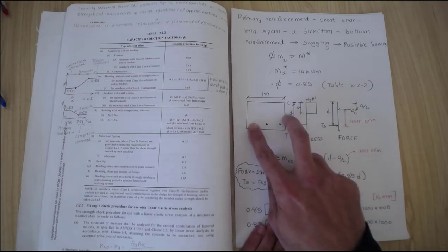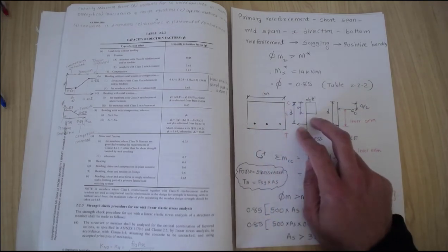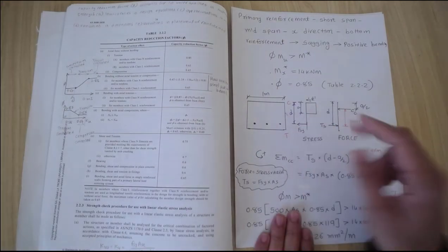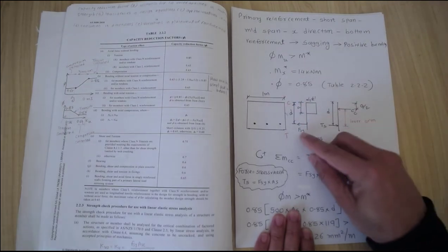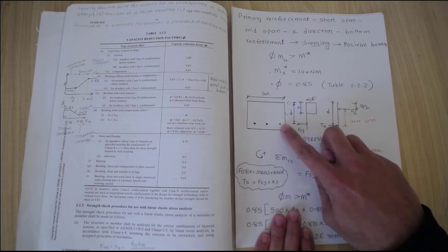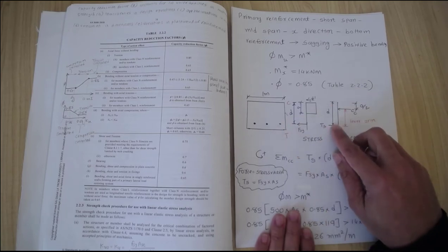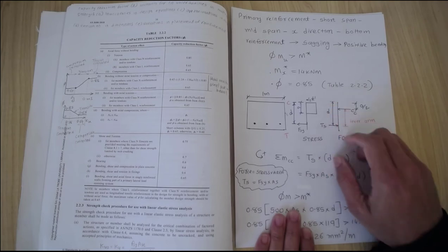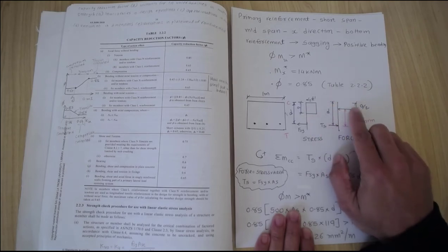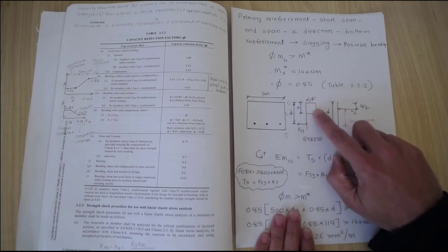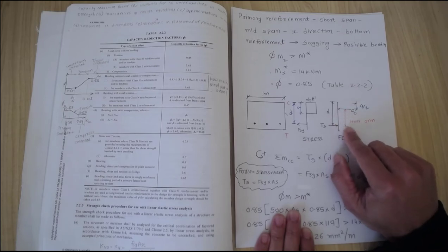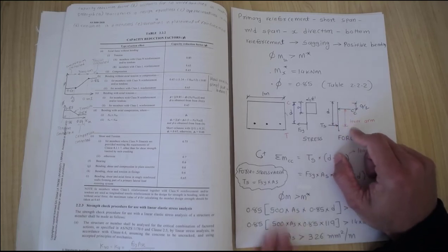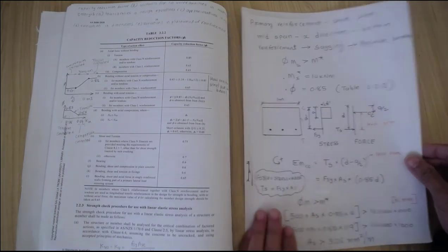Now if you remember this kind of stress block from beam designs, where you have a tension face and a compression face, you have this compression stress and tension stress in the reinforcement, and you have depth d from the reinforcement to the top of the compression edge, and this is the force in the compression. With distance a for the compression stress and d for the tension stress, you have this lever arm, meaning the distance from the steel force to the compression force. Now I need to make some notes on this lever arm.